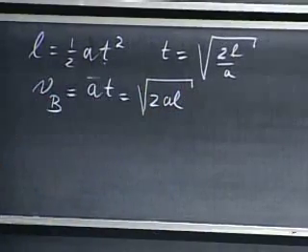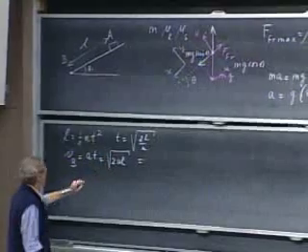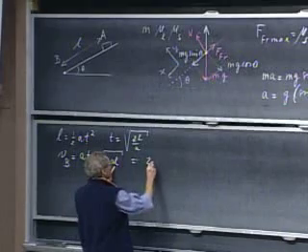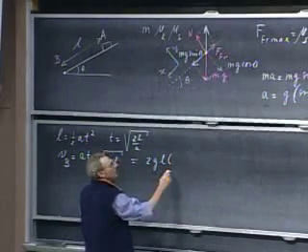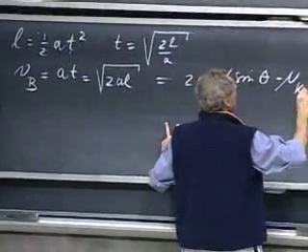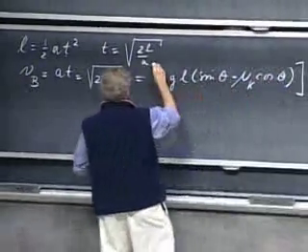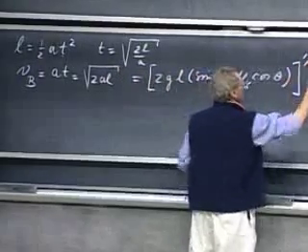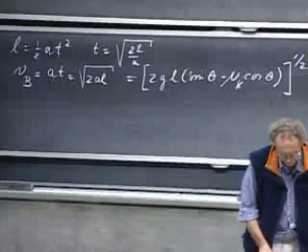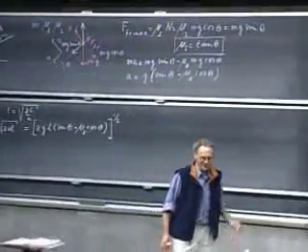And if you want to see that in all glorious detail, then of course you'll have to take that a and multiply that by 2L and take the square root. So we get 2gL times the sine of theta minus mu k times the cosine of theta, and the whole thing to the power 1/2. That is the speed at point B. I, however, would not do it that way. I don't find it very elegant.